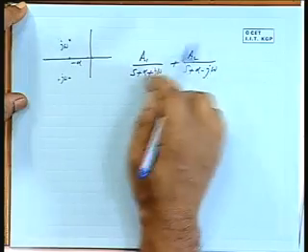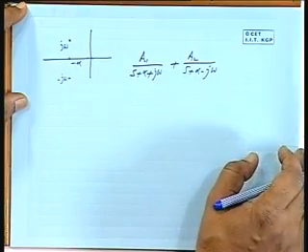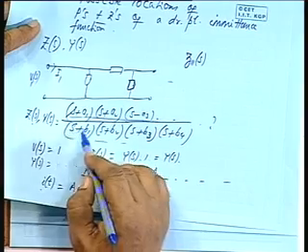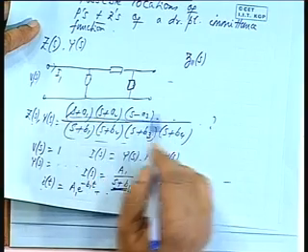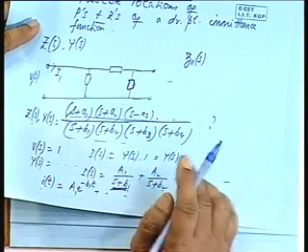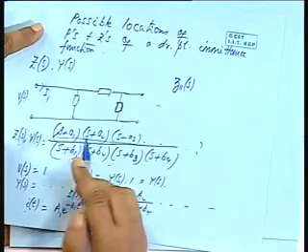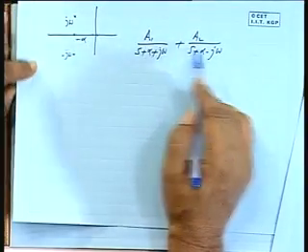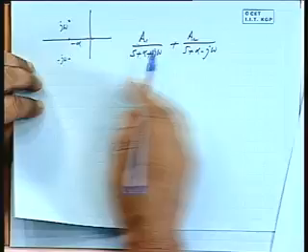Otherwise, if you add it together, the numerator will not be all real coefficients, okay. So, if you are having a network function which is a polynomial in the numerator, a polynomial in the denominator, which have been written in the factored form, and if the polynomial coefficients are all positive, then they must appear, if they are complex, they must appear in conjugate pairs, all right, number 1. Number 2, if you make partial fractions, then A1, A2 will be complex conjugate, it can be proved very easily.